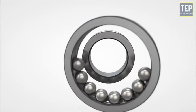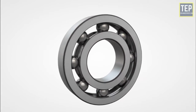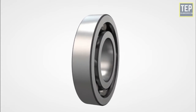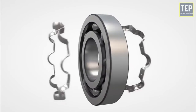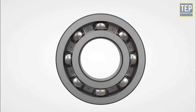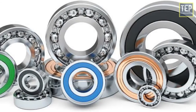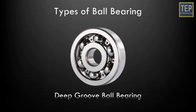Ball bearings provide very low friction during rolling, but have limited load carrying capacity. This is because of the small area of contact between the balls and the races. They can support axial loads in two directions besides radial loads. Depending on the application, different types of ball bearings are available to choose from, such as deep groove ball bearings. This is the most widely used ball bearing.